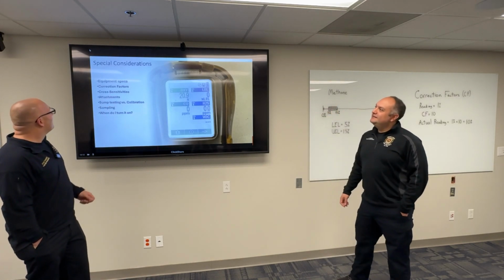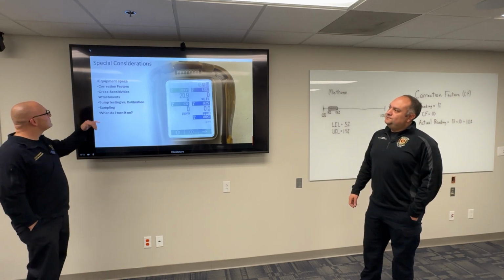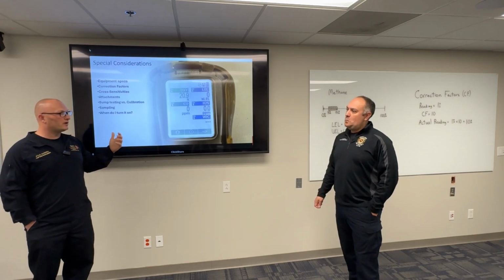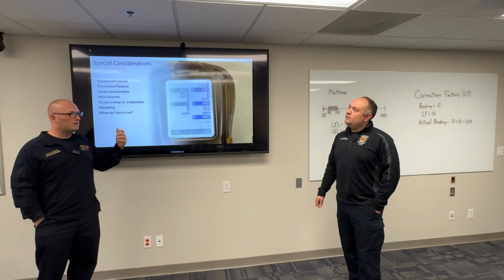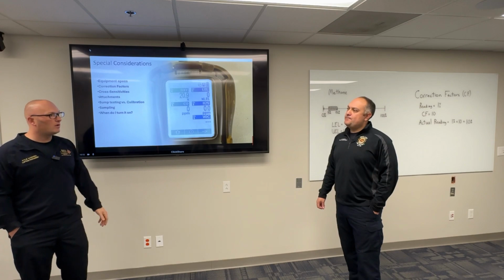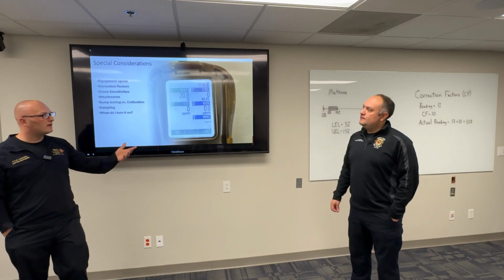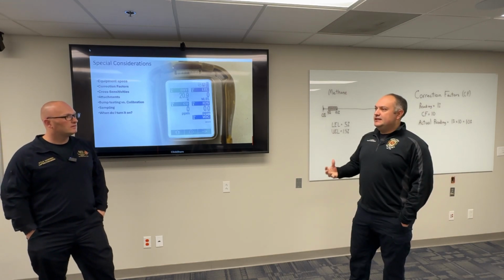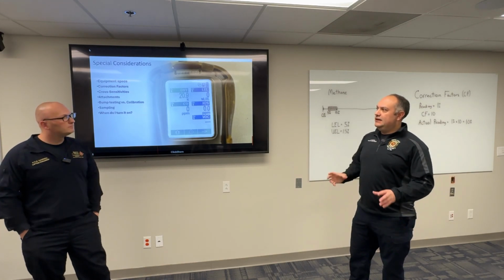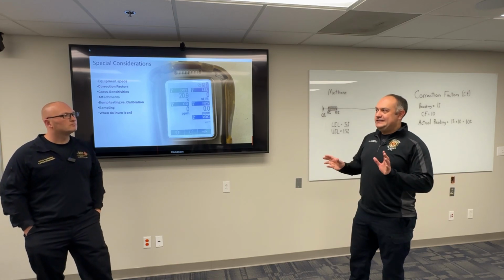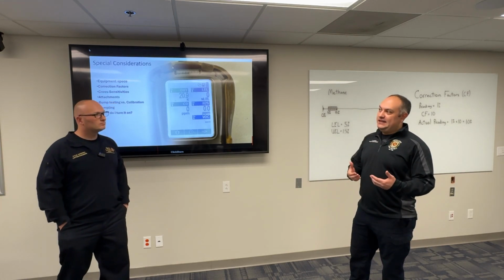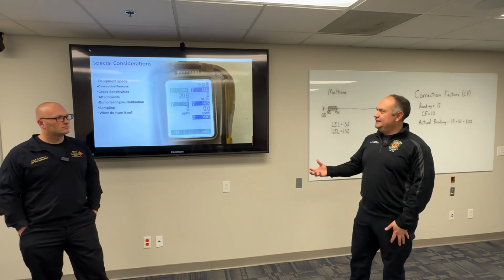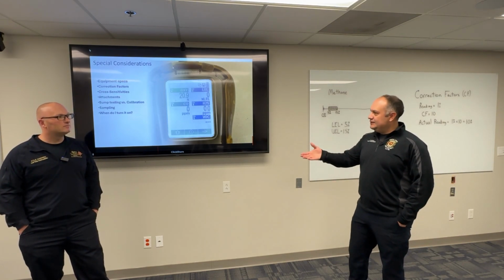Yeah. Some special considerations as we do this. We've talked about our equipment specs, like reading the manuals, knowing exactly what your meters are going to do, what you're going to expect from them, and how they're going to warm up and everything like that. So what else do we have? Just like Kyle said, every instrument is a little bit different. Even with Ray, there's a lot of different things. You think it's the same with the PID lamp, it's 10.6, but one model is a lot different than the other. Correction factors we talked about.